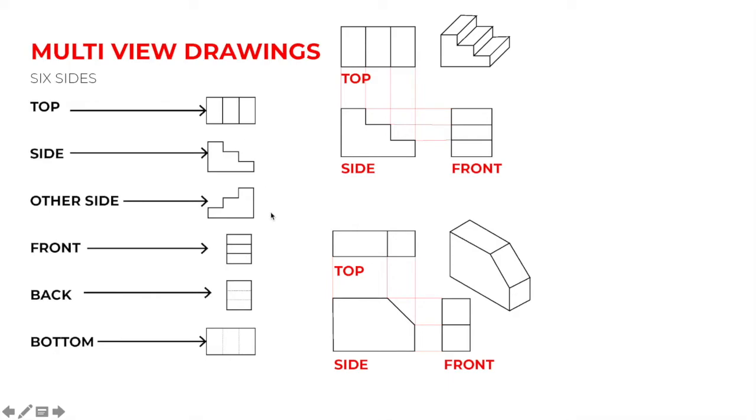Put them all together on a sheet, it gives you a more comprehensive picture of the complexity of this figure. And consequently, any one of these drawings is something that you could measure if you were to fabricate this. Remember that these drawings are intended to communicate not just to ourselves, not just to members of our team, not just to our clients, but to someone who needs to measure and estimate materials for fabrication. So often these drawings need to be able to be measured or calculated or otherwise. Put the drawings together, you can see how the top lines up with the side elevation, how the front elevation lines up with the side, and so on.